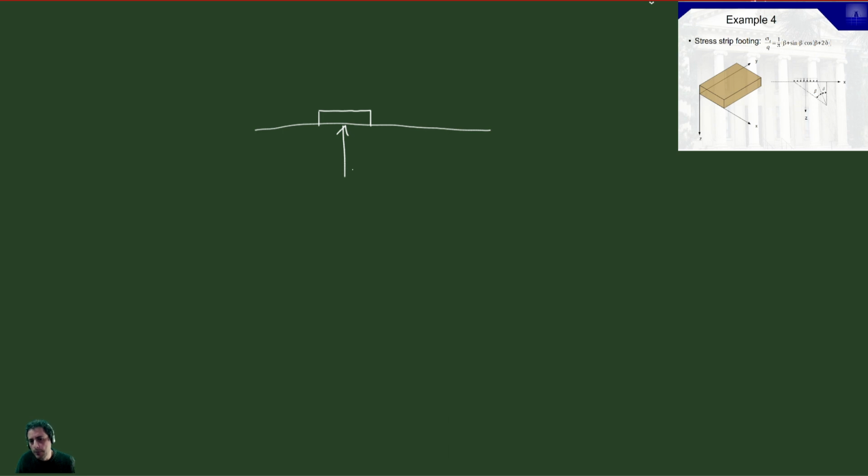But in practice, if we have a sealed, good contact here, water actually has to bypass the footing, right? And so that's why ultimately we'd rather use a 2D consolidation solution, so that we would be able to model the path of water like this.